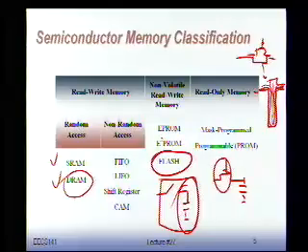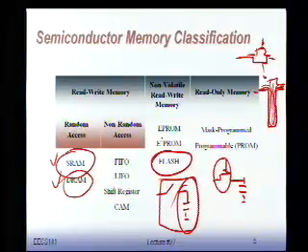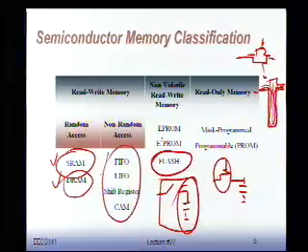The only thing that really typically appears on a chip is this SRAM, because that's the fast access. Having this SRAM sitting very close to your computational logic is very important from a performance perspective. So that's why if you look at most chips, you will see big chunks of SRAM there. And SRAMs can be designed without doing very special technology tricks. It's really a design trick. Okay? So all those other ones are important, but from this class perspective, I think focusing on SRAM is the most important thing. By the way, there's some other memories that exist which are non-random access.